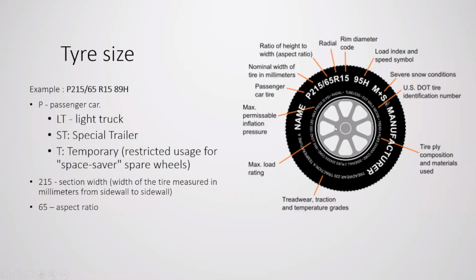So actually I included one small mathematical calculation for your previous year batch, just to calculate the speedometer error once you replace the tires with a different tire size. Right? So it is a simple case, right? So normally you can get the tire width and the diameter using this code. Then you can simply use the C equals πD equation to calculate the peripheral length, right?